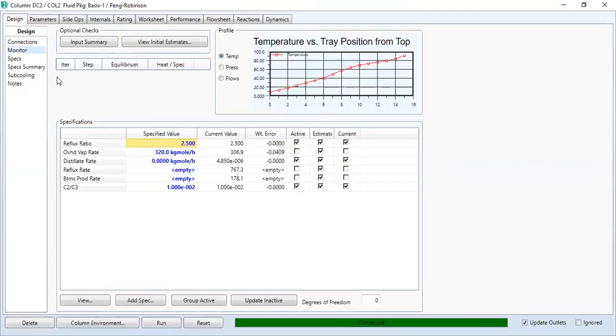As we know, to solve any distillation column, you should make the degrees of freedom 0. So with the partial condenser distillation, you have 3 pieces of information to give. In this case, we give a reflux ratio, which is 2.5, and the distillate rate, which is the overhead from the distillation column, we give as 0.